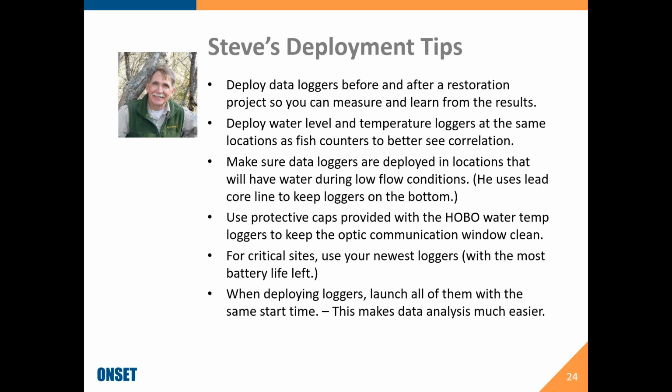And another point is when you launch the loggers or start the loggers, launch them all with the same start time. This makes it a lot easier to analyze the data afterwards. That way all the readings are lined up with each other in time.